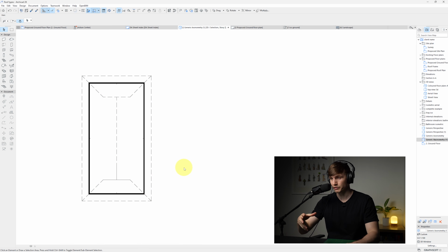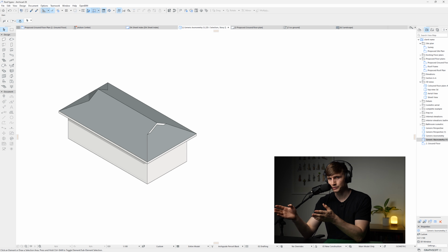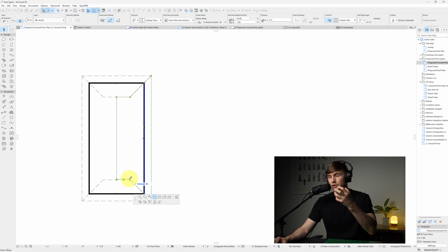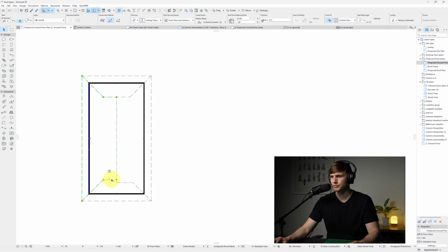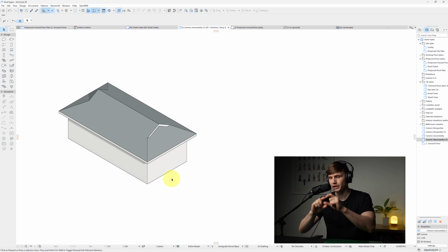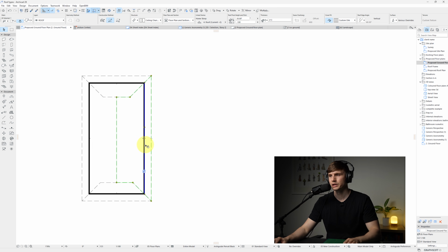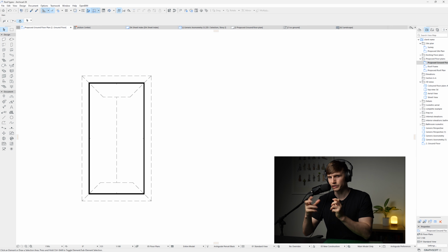Now when we go into our 3D view, we've now got our Dutch gable, which we can adjust. We'll delete these polylines, and we can adjust this gable back and forth. Say if we give it 250 mil, and we stretch this one out as well, we can make that a larger point at the top. Now the trade-off with this method is that each of your roofs are now a single plane. So if you want to modify the roof, there's a little bit more manual work involved.